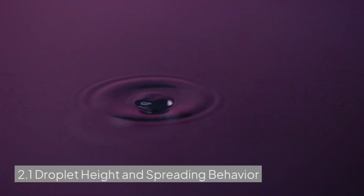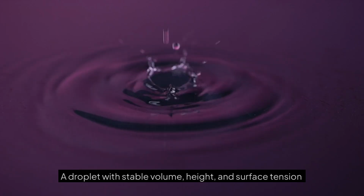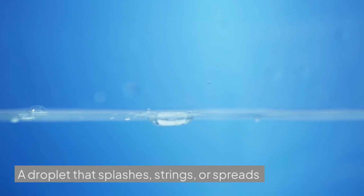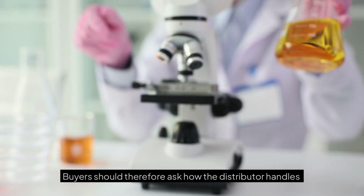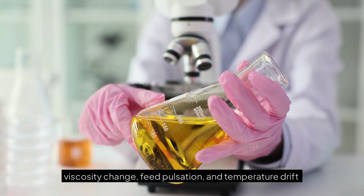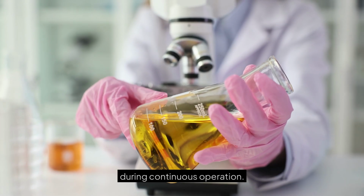2.1 Droplet height and spreading behavior. Pastille shape begins at impact. A droplet with stable volume, height, and surface tension can form a repeatable dome. A droplet that splashes, strings, or spreads unevenly creates inconsistent particle height and contact area. Buyers should therefore ask how the distributor handles viscosity change, feed pulsation, and temperature drift during continuous operation.